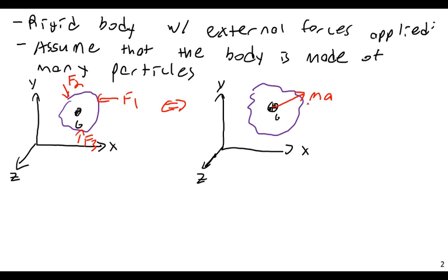These are equivalent back and forth: a mass times acceleration on the body, and an H dot G, so a torque, essentially, or a rate of change of angular momentum, or a moment. Actually, maybe I could just say there's a sum of forces here, and then there is a sum of moments about the center of gravity.